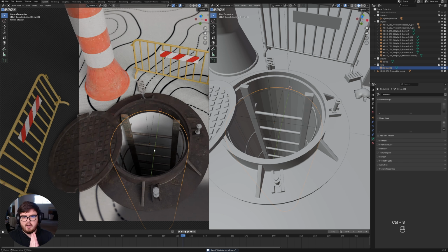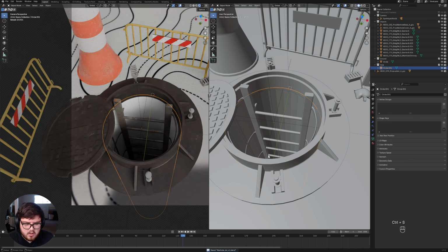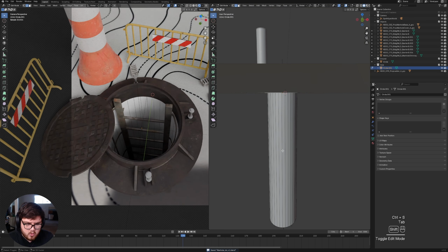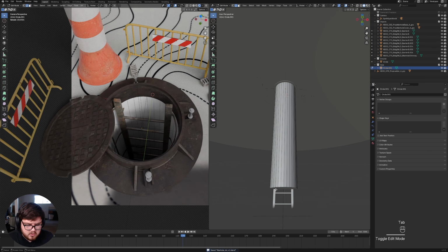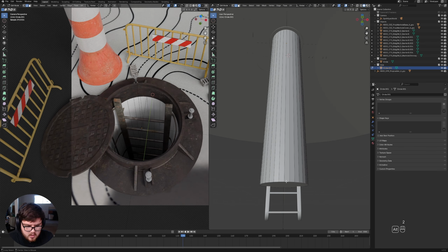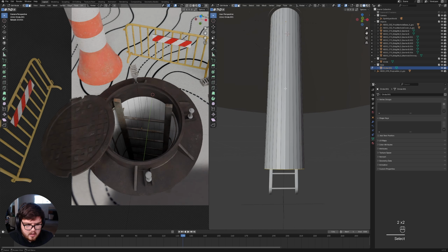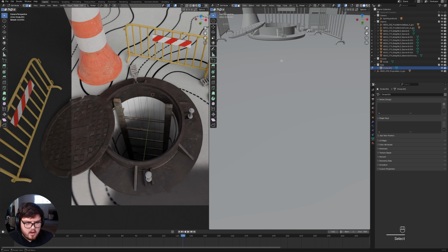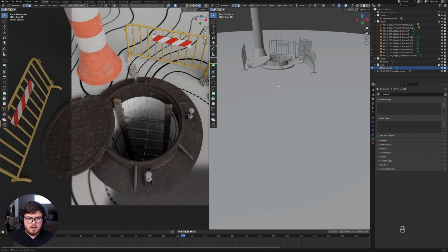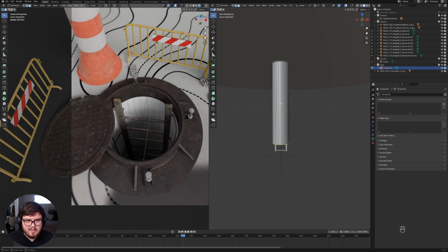Now, of course, you can download the texture as I have it down below. What I'm going to do is we'll go ahead and UV unwrap this ourselves, because it's going to be super easy like that. I'm going to select the bottom of this, and then I'm also going to select the edge loop right here. That is one that we're not going to see on camera, and that is going to be the edge where there's going to be a visible seam. You want to select an edge that you're not actually going to see on the camera. So we'll hit U and mark seam. That'll mark the seam.